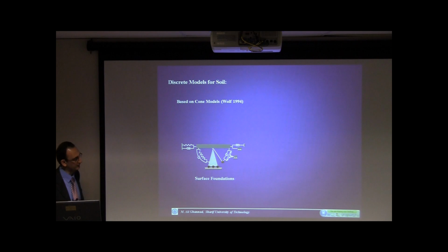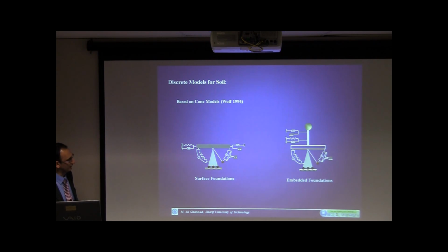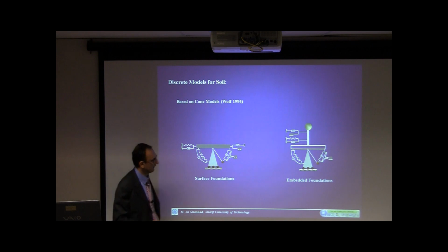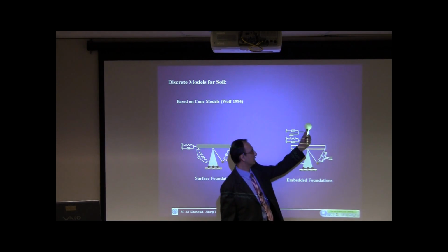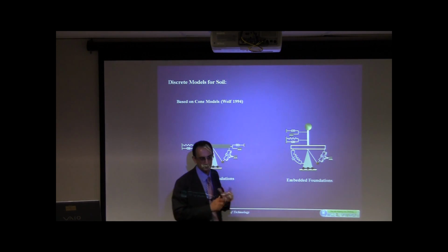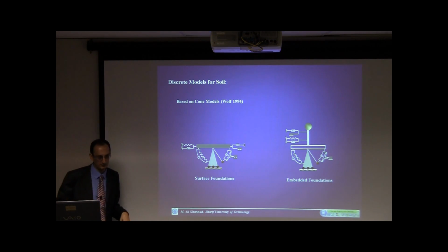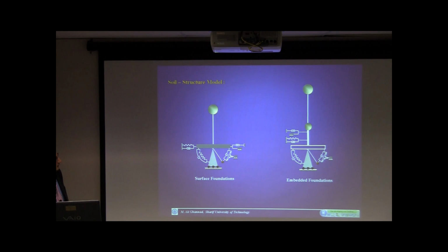And that's the reason that we use that model. This is for the surface foundation, and this is for the embedded foundations. This is not the structure, it's the mass of the foundation, and the eccentricity here provides the coupling between the sway and rocking stiffnesses, okay? And we can construct the superstructure here and analyze it.